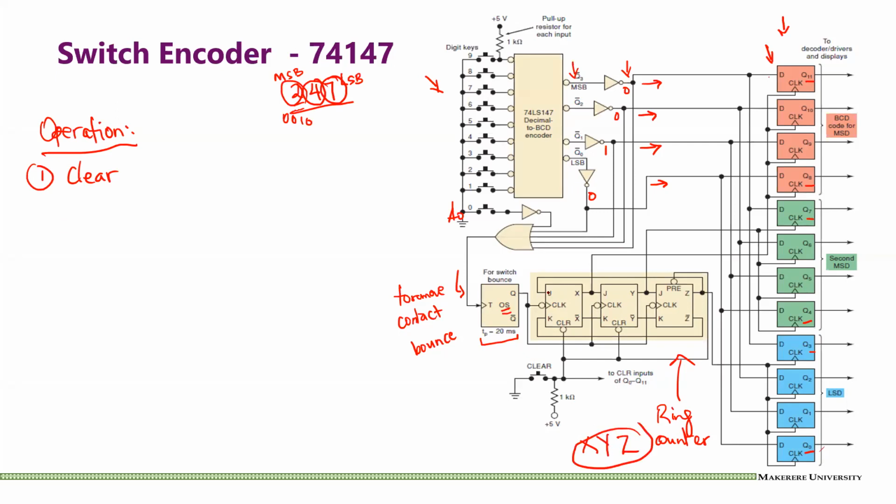The value at the output Z is fed back to the input. This is how a ring counter works, and we know that that is quite different from how a Johnson counter works. The Johnson counter would have Z inverse going back, but this is a ring counter, so it's Z itself, the output, going back.